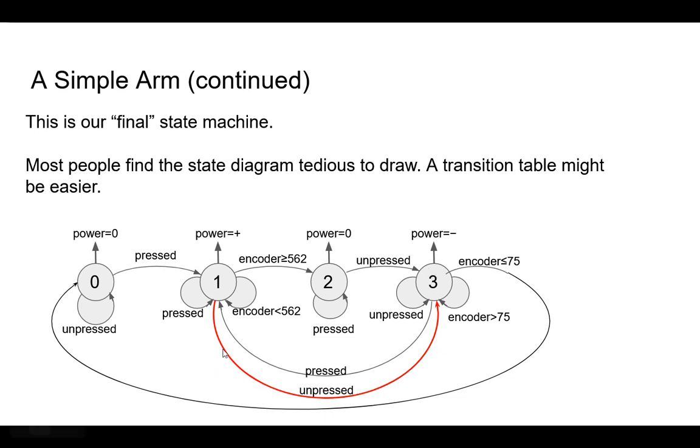And by the way, I think this is a dandy way of doing operator control because suppose that the operator wishes to put the arm down, let's say, to grab something. Then another robot gets close, and so she becomes afraid that the other robot's going to break the arm. All she has to do is take her finger off, and then that arm goes back up through this state to a safe position, returning back over here. So I think that's a great human factor interface.